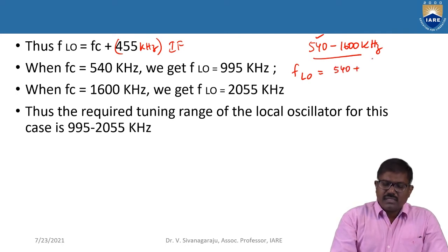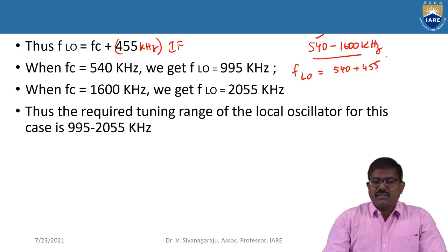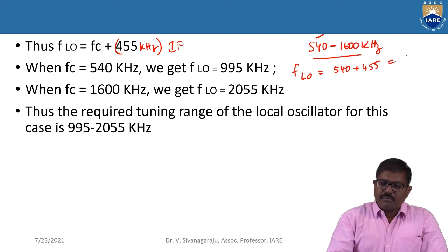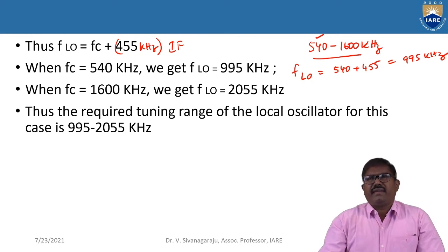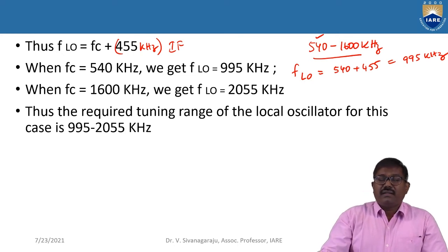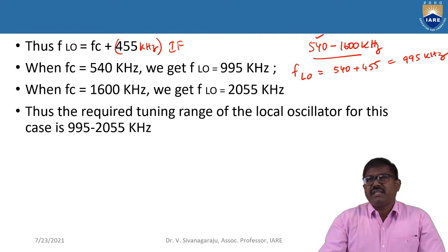540 plus the intermediate frequency, that is 455 kHz. So when you add them up, you get 995 kilohertz. And the last tuning range of the frequency is 1600.